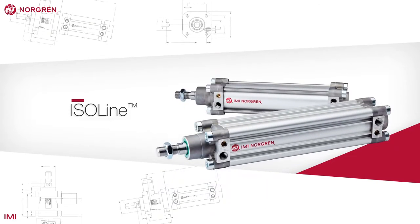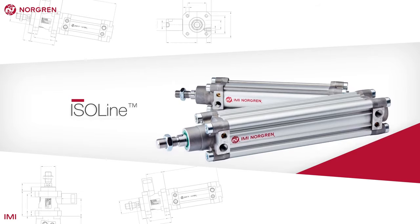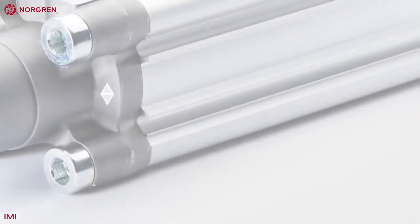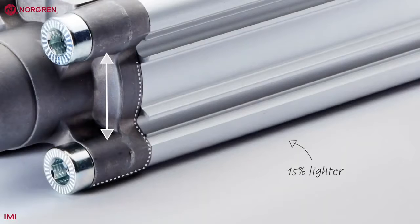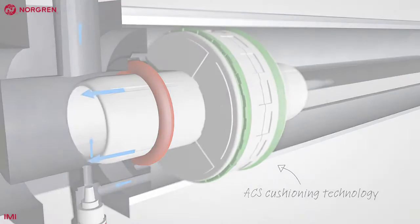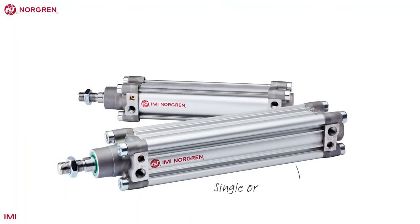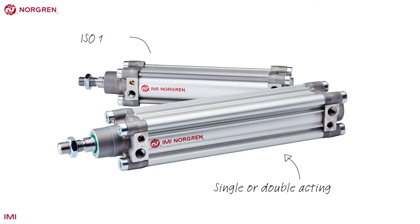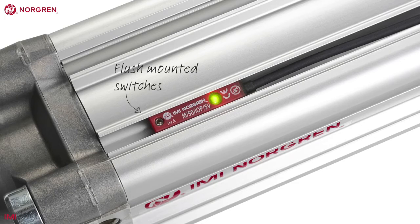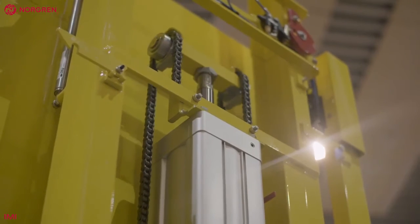The ISO line is a significant improvement over its predecessor. The cylinder is 15% lighter and with ACS cushioning technology. Available as single or double acting, it conforms to ISO 15552, has flush-mounted switches to avoid damage, is fully configurable, and comes with a magnetic piston as standard.